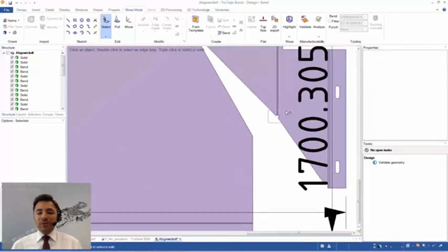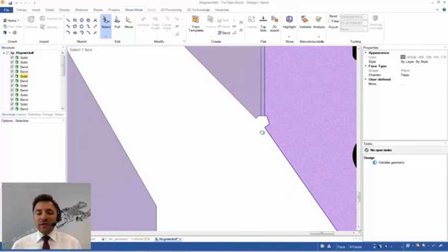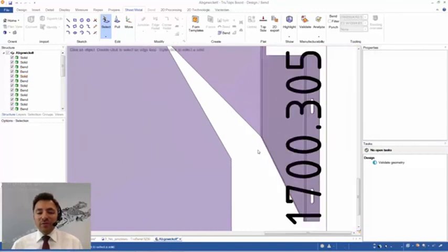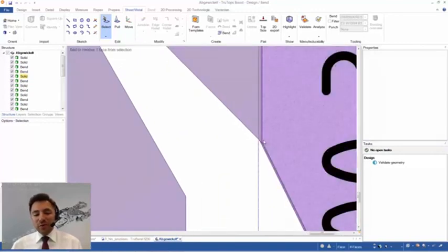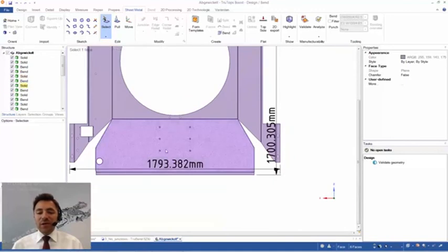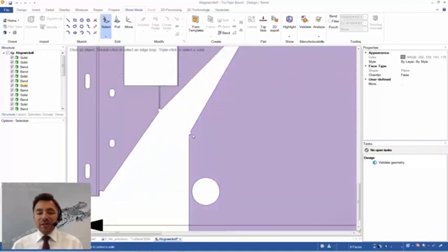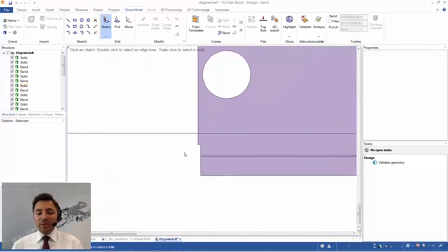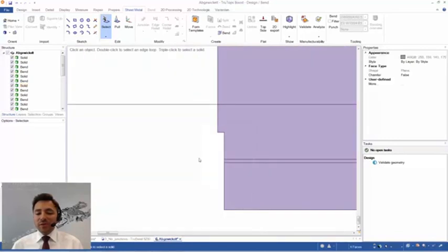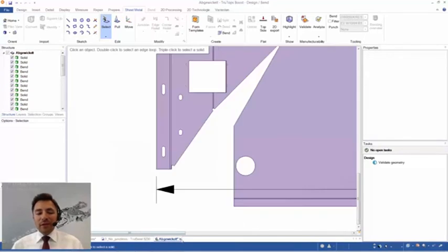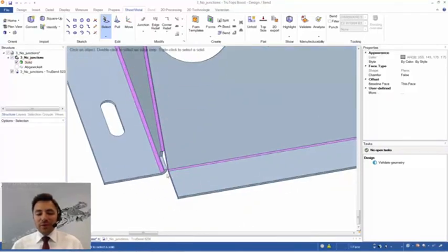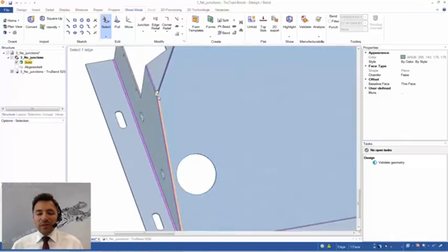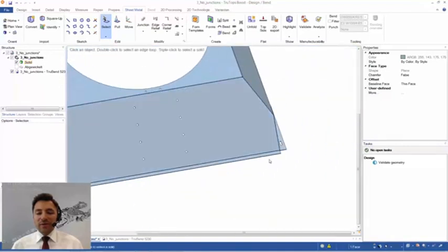So of course the automatic preparation is very useful. So that relief should be there, so I just reverse it. But the tool gives you full control with the manual tools. So just correct some reliefs you don't like by selecting them, hitting fill, and you see if you close the part how nicely the corner reliefs are.